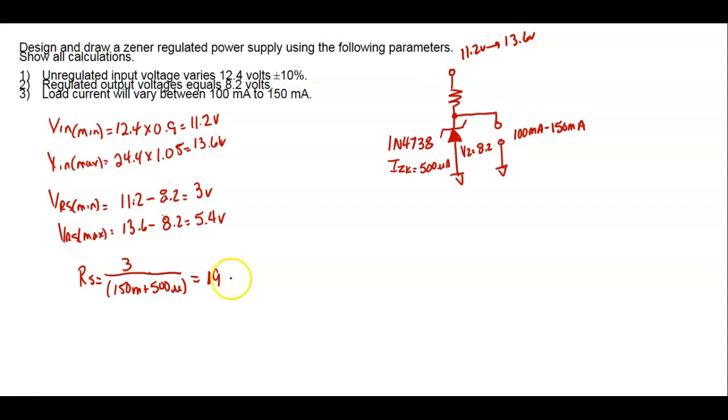19.93. Yeah. So we can use 19.9. That's okay. But on zeners, this is a little different. On zeners, we never do what? We never go up. Well, it might have still worked out, because 19.9 and 20 is okay, so you still had a chance of choosing the right resistor. But if it was 19.5 and we round up, then you might have chosen the wrong resistor, right? You understand? So here it's probably no big deal.